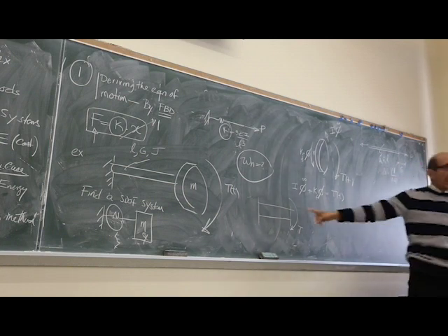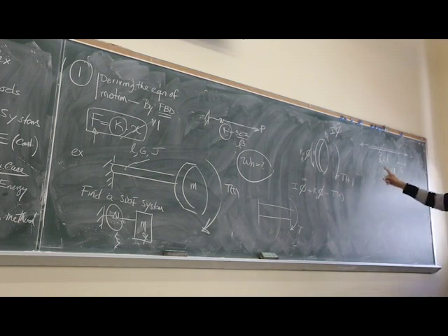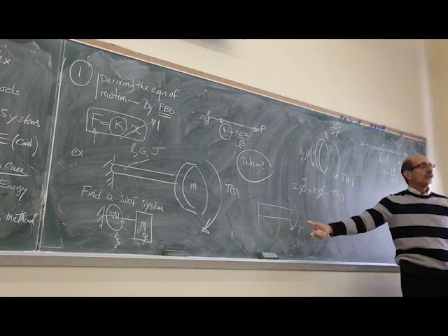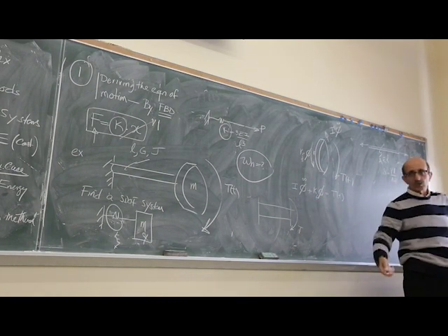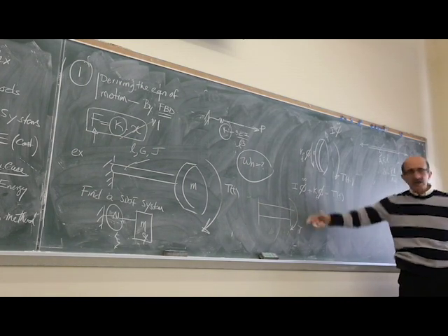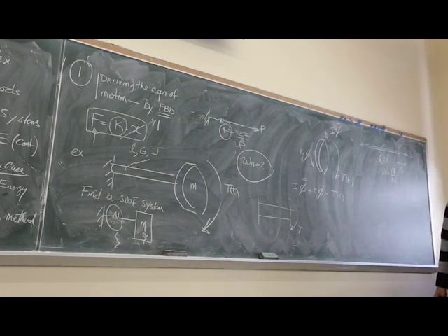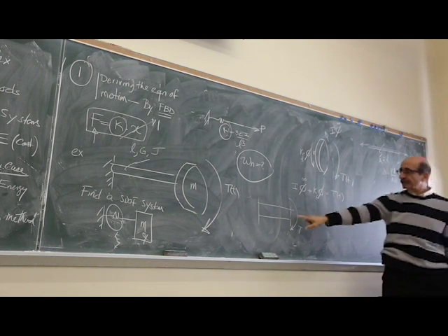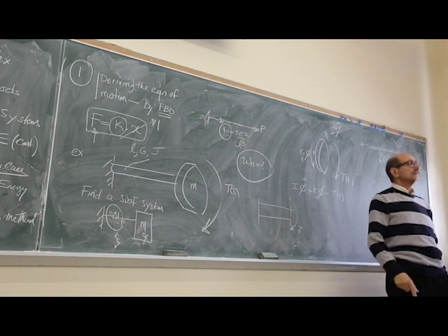A shaft is analogous to a bar. Here you have an axial load stretching the bar in rectilinear direction. Here you have a torsional load or angular load deforming this bar in the same direction as the moment of the torque applied. Deformation takes place in the same direction that moment is applied.